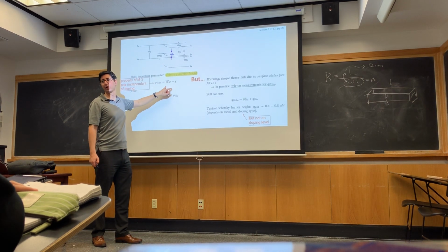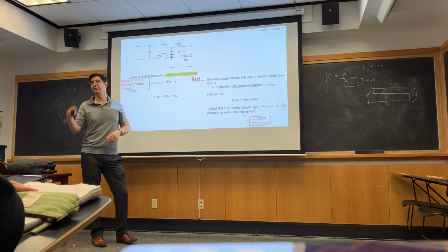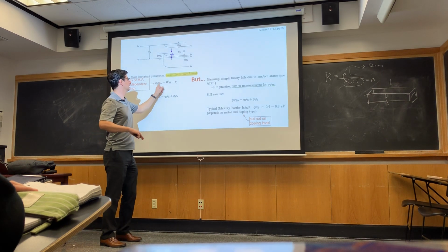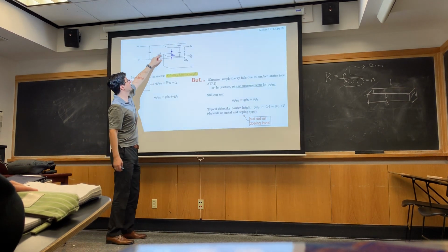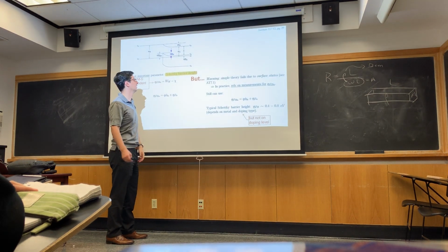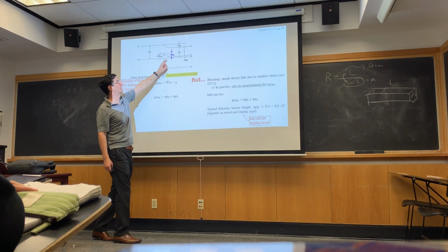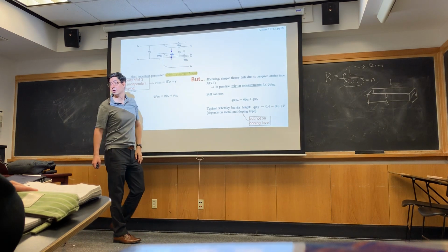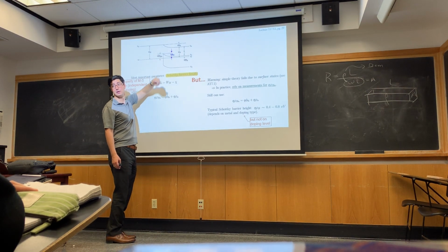But this falls apart if there's any non-idealities, if there's any defect states at that surface. And in fact, we typically don't get this barrier height. This is called the Schottky barrier height. It looks like a barrier to getting electrons into this device. This Schottky barrier, and this is saying for an n region, because I have an n region here, is a Schottky barrier height to the conduction band. Okay, I could also have q phi Bp.